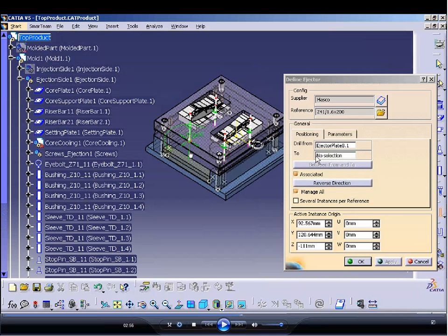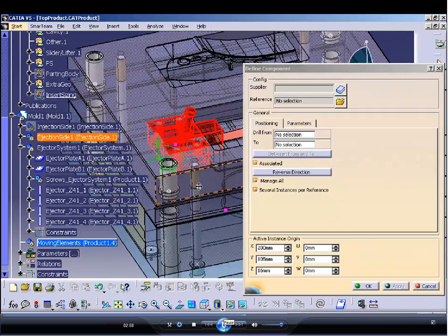We even have rules set up so we'll pick the right location for the ejector pins and how many you should use, whether you should be using lifters or whatever your company standards may be. We can capture all that information. So it will also trim back these ejector pins. We also have anti-rotation inside the ejector pins.